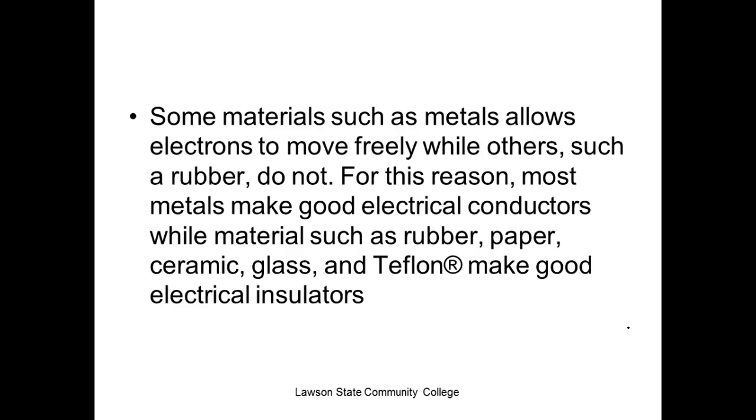This is another slide, but what do we need insulators for? Yeah, to keep you from getting electrocuted, right? It allows us to handle conductors, right? Plus, it allows us to bring conductors in close proximity to each other. We have to have insulators if I'm going to run a cable. So what is a cable? Well, a cable is a group of two or more conductors that shares a common jacket. If we're going to put two or more conductors inside there, every one of them is going to have to be insulated. So it allows us to handle that stuff.